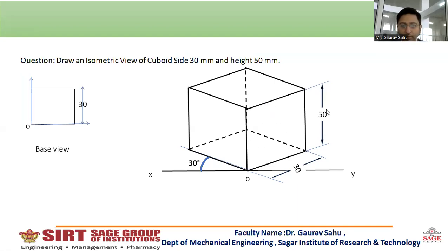Now let us look at the pencil work. All these visible lines should be made by an HB pencil. Dash lines should also be made by an HB pencil, because these are actual lines. Okay. The projector lines, like the way I have marked the projectors for the dimensioning line, these projectors should be made by a 2H pencil. And this dimension line should be made by an H pencil, these dimension lines. You can easily see how I have marked the projector. And this angle should be very much signified. This is the actual answer to your question.